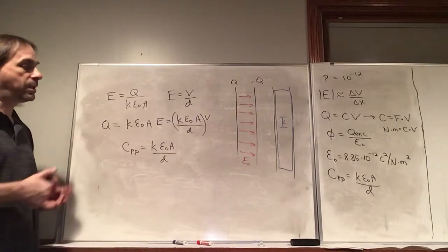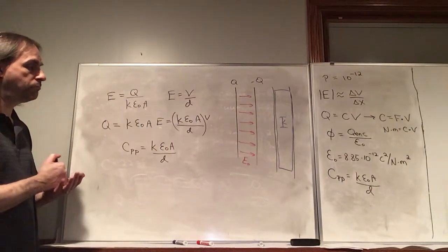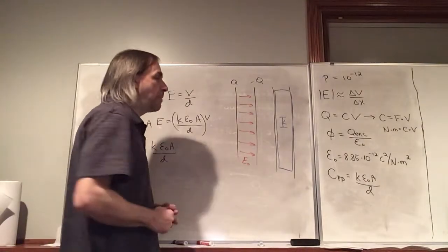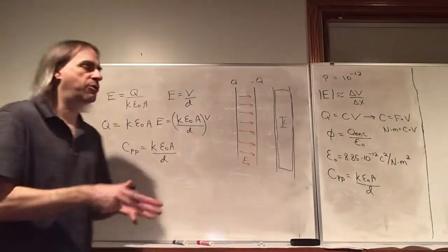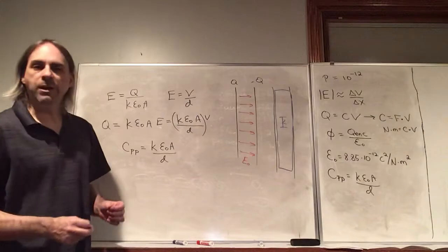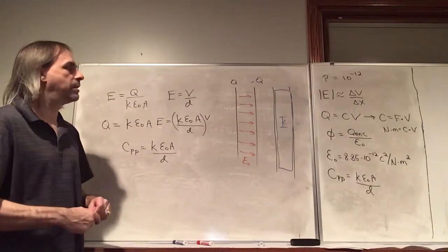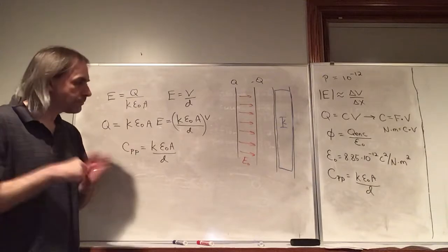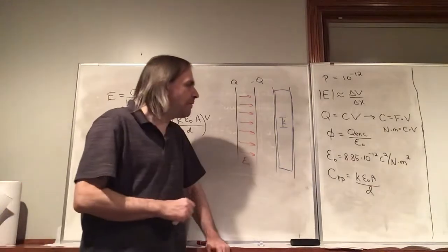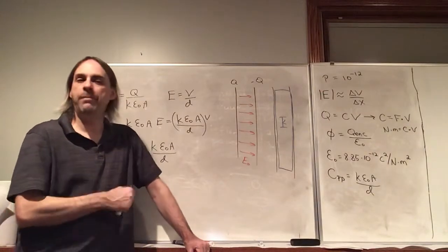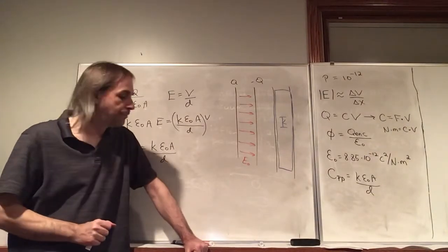Okay, so that's one way you could increase the capacitance. Because again, we had a fairly large capacitor, and we just barely measured something in picofarads. Or maybe we want to get to nanofarads, so that's still a big factor. And so it's a fun way you could build a more compact parallel plate capacitor.